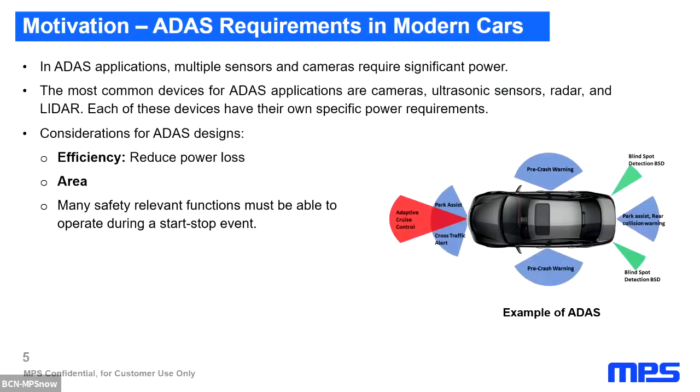As it's known, Advanced Driver Assistance Systems, also known as ADAS, are of high interest in today's automotive market. Nowadays, the number of sensors and cameras placed into this kind of design is increasing a lot in order to monitor every single part of the car. As a consequence, there is also an increase in the power demand of ADAS. On the other hand, each sensor inside these systems has its own specific input voltage requirement, for example, around 10 volts in cameras. That is, the battery voltage must be down converted to different voltage levels to supply the required power to all the system.